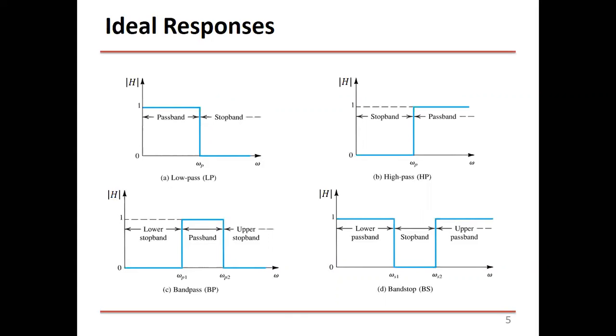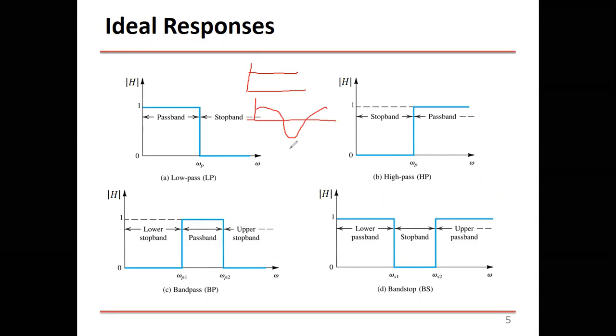Why do we call it a filter in the beginning? Because it filters out noise or something? No. What about phase? Yes, this is the answer. The all-pass filter doesn't care about the gain response. The gain is flat. But the phase is not linear, or the phase might be like something like this. So you compensate the phase. You build this filter to equalize the phase.